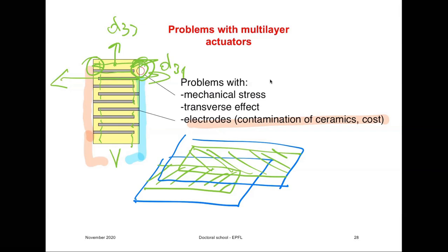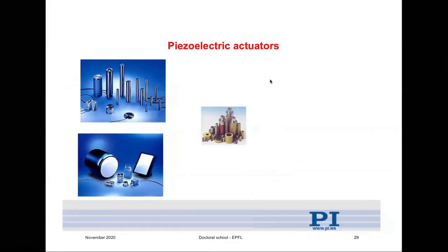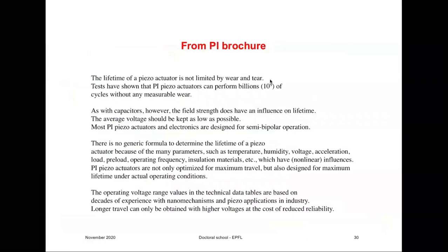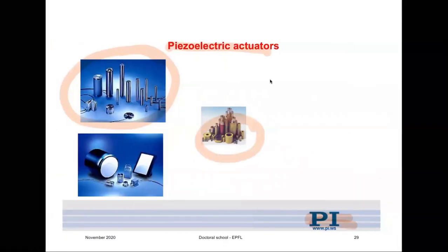So one of the things is don't apply negative field against the polarization, and you usually buy from the producers a power supply to electrically drive them, which doesn't allow a voltage which would depolarize. Here are pictures of some of the piezoelectric actuators from Physik Instrumente, one of the largest producers in Europe. You see the metal, the steel parts, and the ceramics are inside. Here you can see some of the ceramics, how it looks like.